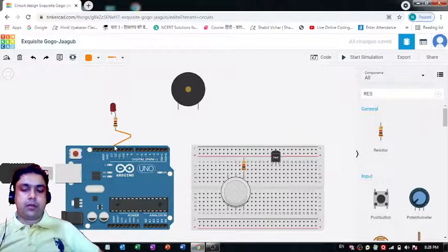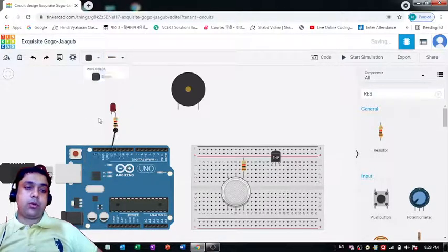It's a free pin to which we can connect this anode point. Then we have this cathode point. As you know very well, because we need to give it a negative charge, we have to connect it to this ground pin. Like this we can do it. I'm changing the color of the wire to orange.